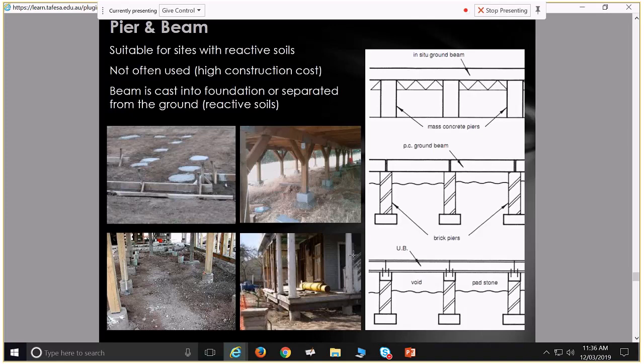Next thing we're looking at are a suspended timber floor and suspended steel floor. With our suspended steel floor and our suspended timber floor, we're going to have a footing system like this, where we can't just, actually no, you can. You can just auger holes, and then you ram posts in, so you can ram timber posts in. You still see that happening with CCA treated timber. CCA is copper, chrome, arsenic. It's that green timber. Does everybody know what CCA is? Seen it? No?